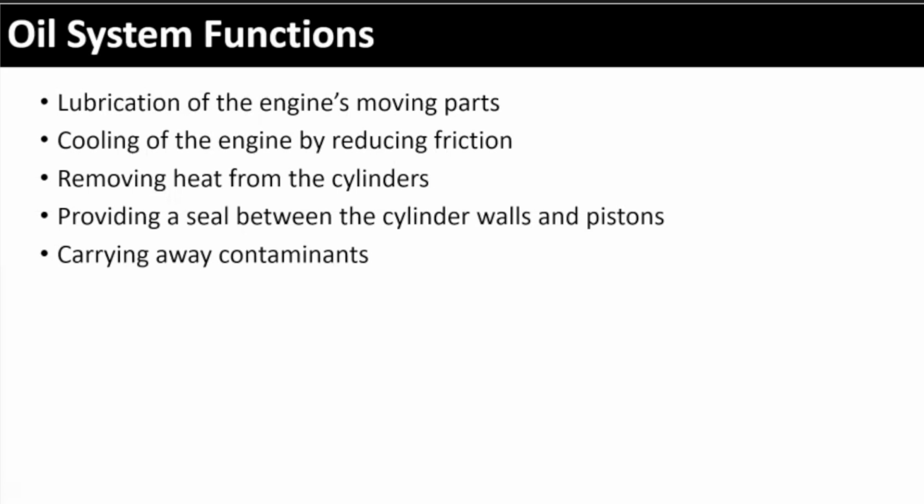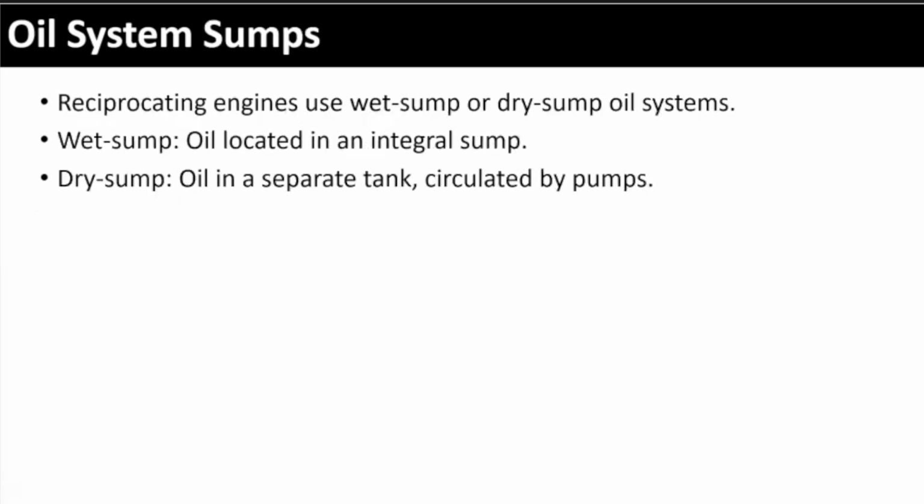Lubrication and cooling, right? We just finished that part. We can skip through about 50 slides here. All right. Two different types of systems, wet sump and dry sump. Wet sump essentially just means that the oil is in the engine itself. A dry sump means the oil is in a different location and it's pumped into the engine.